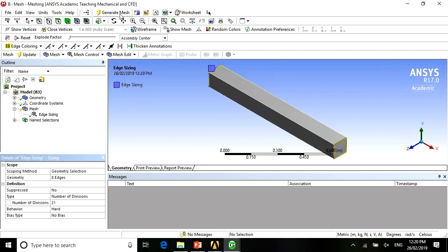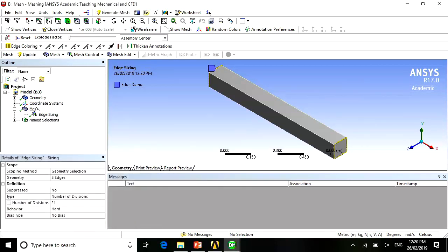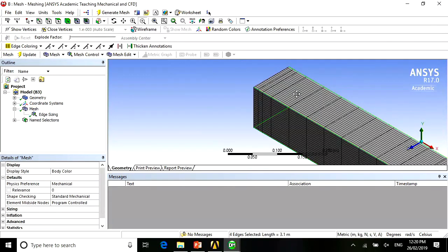So I'm going to regenerate the mesh, all right? And I'm going to let you have a look whether I've done it. Okay? Notice, if I zoom in here, you see what the software has done is that it has got the face right, but along the length itself, it sort of put more mesh towards the inlet itself. Okay, so this is how automatically it tries to do. It tries to resolve the mesh where you have the activity coming in, right?